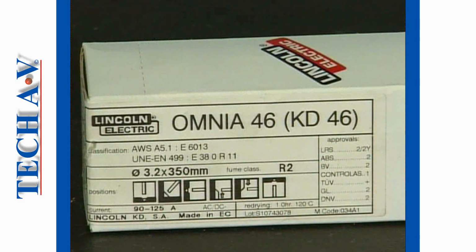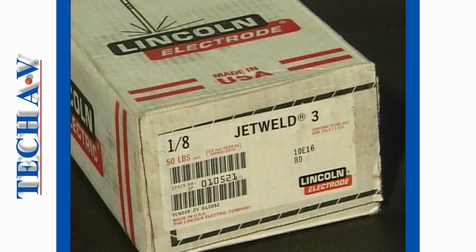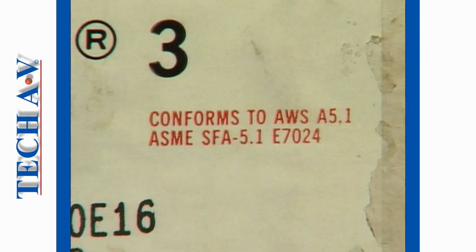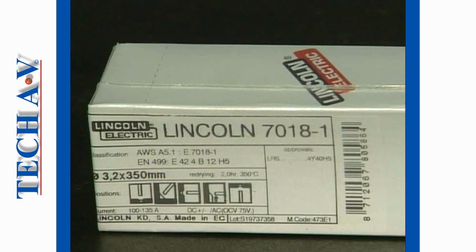A very common electrode is the E6013 type, also known as a general-purpose electrode. Other electrode types are suitable for special purposes, such as out-of-position welds, and those designed specifically for direct current used on thin plate and pipe work.